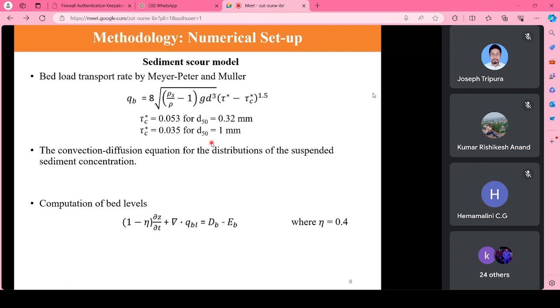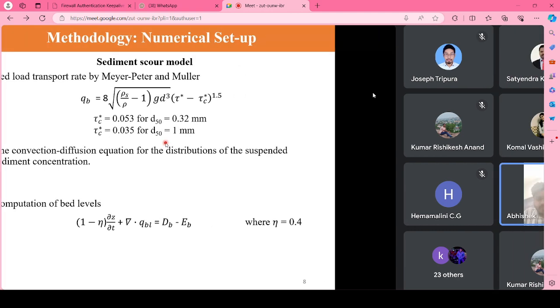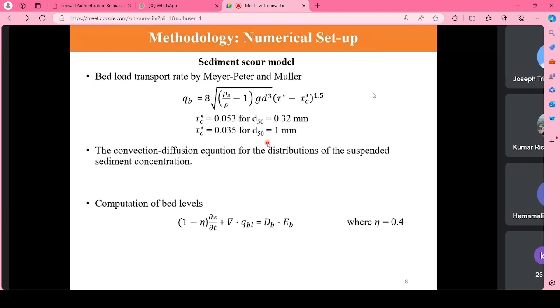Theoretically, the river bed is composed of a variety of particles, so you will have a grain size distribution, but for the numerical model, the case is simplified and the entire bed is represented by D50. That's a major drawback of the numerical model. Of course, you can use various layers of different bed materials, but for the simplified case, D50 is taken and it represents the entire bed of the channel junction.